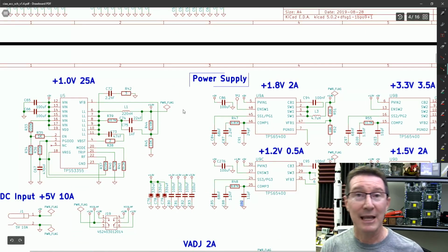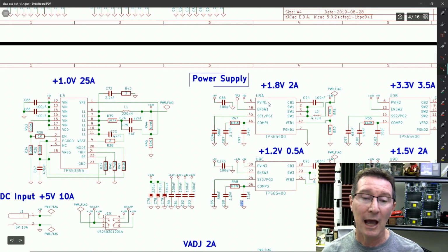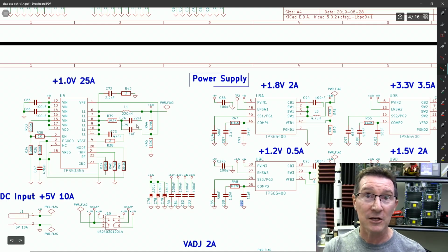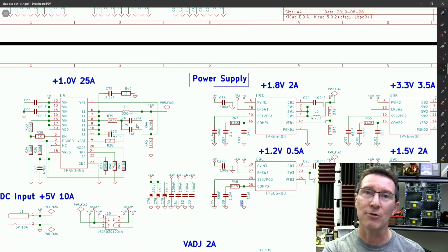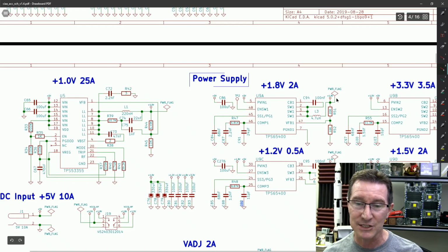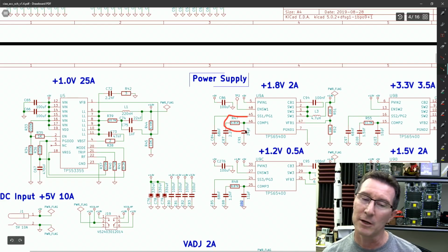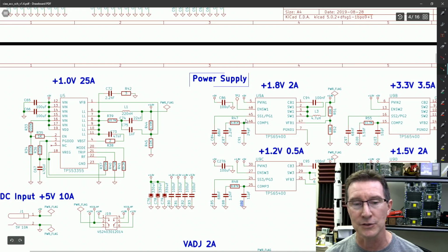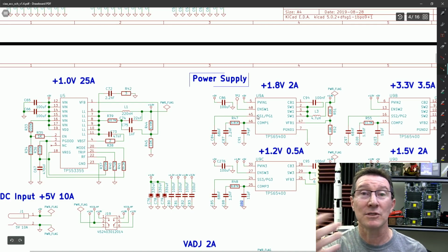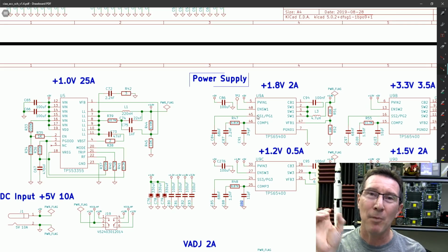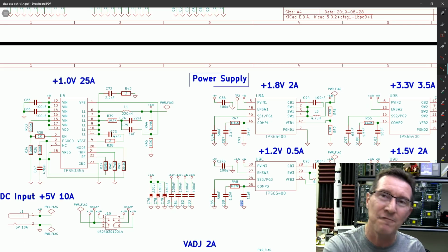And there's some argument over when you might do this. Some people might actually, okay, go and the number pops out of your computer, so that's what you put in your schematic. And then, and I've done this myself, and there's valid arguments for it, once you've done that, then generate your BOM and then go in and see if you can optimize the BOM. You can actually do it right at this schematic stage. While you're designing, oh, I'm not going to use a 6.81K anywhere else, so I'm going to put two resistors in series or parallel to get near enough value or something like that. So you could argue that it's better to do as a separate pass, because then you're not bogging down your design process. You're getting the design down first, and then